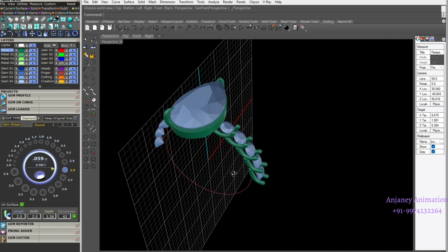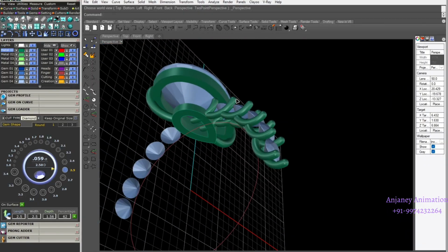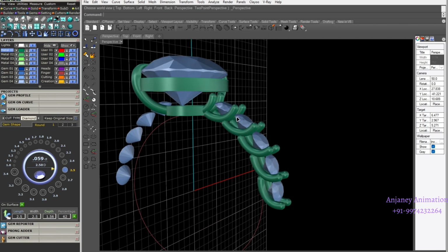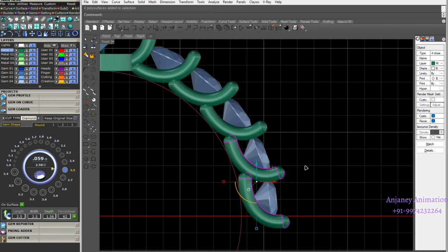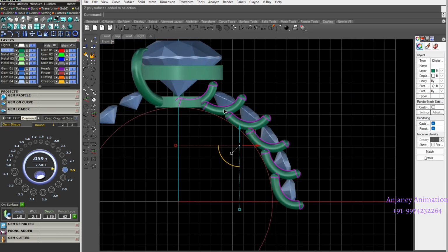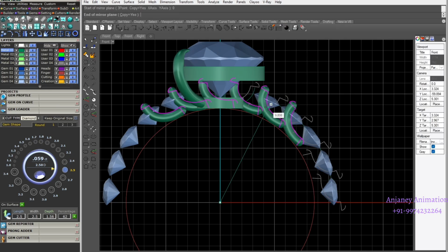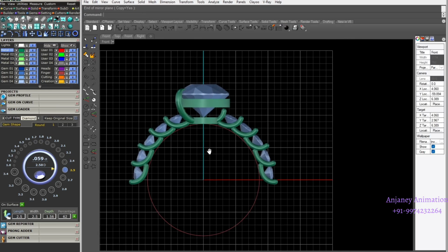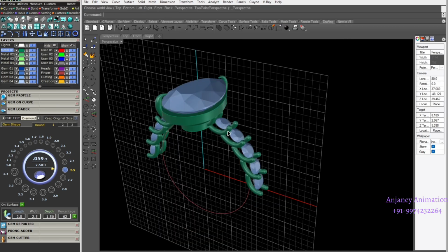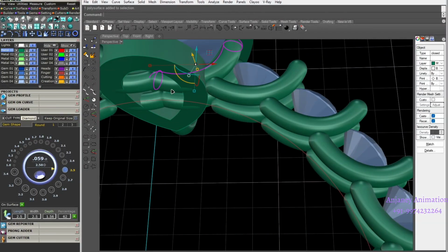If both sides are symmetric, then using front view, side view, or top view for mirror or copy position will be very useful. So now select these prongs and let's mirror them to the other side. So this is a symmetric option. Let's mirror with 0, enter, and then click on the second upper side. So this way we can mirror the object.